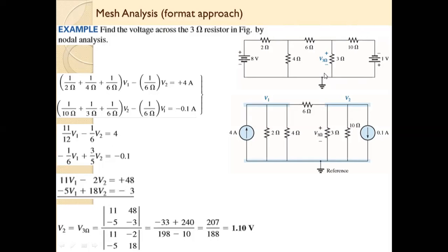We remember, if any voltage source or voltage sources are given in a circuit and you need to apply nodal analysis, then first you need to convert the voltage source into a current source. I already explained in previous lectures how to convert a voltage source into a current source. The method is very easy. A resistor which is placed in series with the voltage source, we will place in parallel, and the voltage source would be replaced by a current source using Ohm's law.